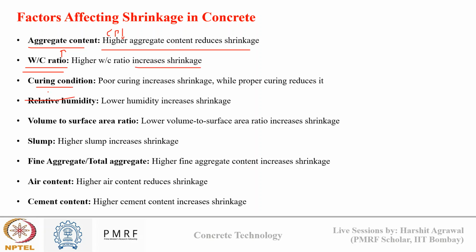Curing condition: if we cure the concrete properly, then we will have a dense microstructure, so shrinkage will reduce, while poor curing will increase the shrinkage. Relative humidity: if there is low relative humidity, then evaporation loss will be higher, so shrinkage will be higher. Volume to surface area ratio: if I have a higher surface area of concrete, then there is more surface available for moisture loss, so shrinkage will increase.